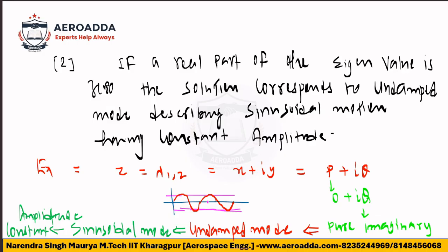Now, for longitudinal dynamic stability, I have discussed two types of oscillation: short period oscillation, SPO, and long period oscillation, LPO. I explained this in the last class. The long period oscillation is also called phugoid motion, PM.